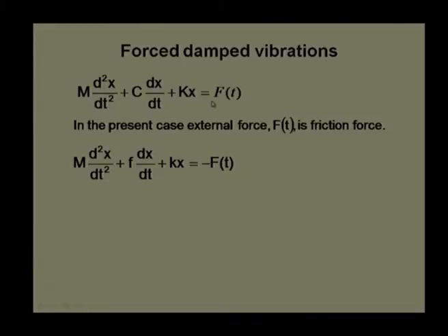This is not making the motion, it is a resisting motion. We know the friction force resists the motion, that is why the negative sign has been introduced here, and we need to find the expression for F, how the friction force is varying with time. We initially consider two cases, when the friction force was changing immediately from one position to another, from Fs to Fc. In this case, we are assuming some sort of linear profile, it changes gradually. It is not happening immediately from Fs to Fc.